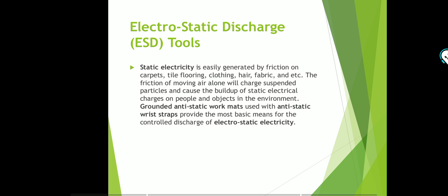Electrostatic discharge or ESD tools. Static electricity is easily generated by friction on carpets, tile flooring, clothing, hair, fabric, and so on. The friction of moving air alone will charge suspended particles and cause the build-up of static electrical charge on people and objects in the environment. Grounded anti-static work mats used with an anti-static wrist strap provide the most basic means for the controlled discharge of electrostatic electricity.